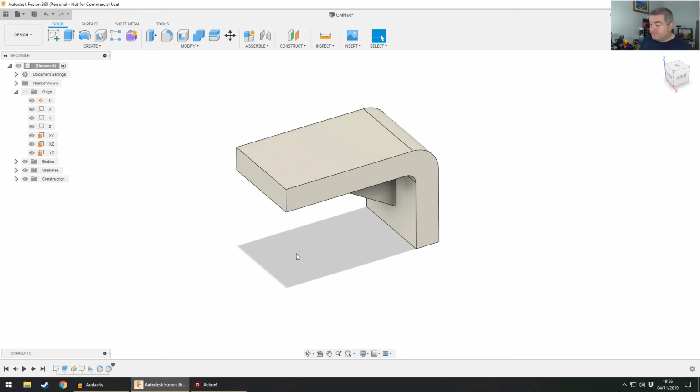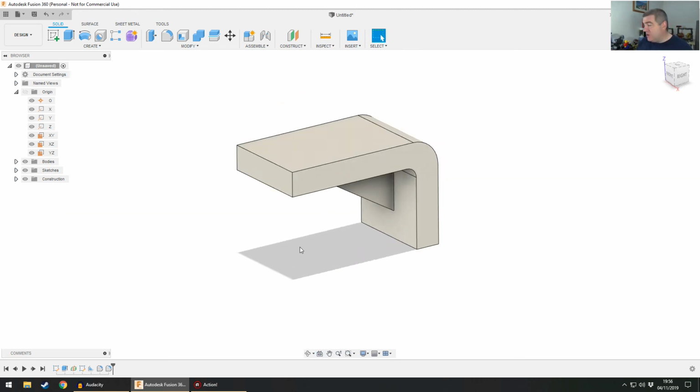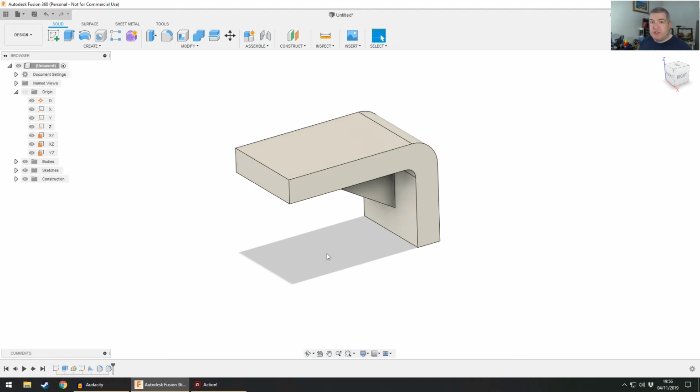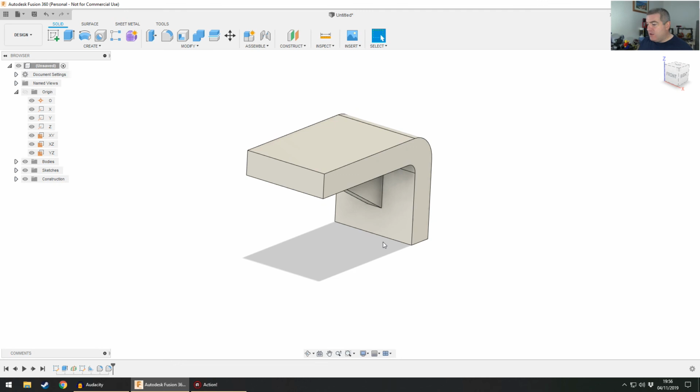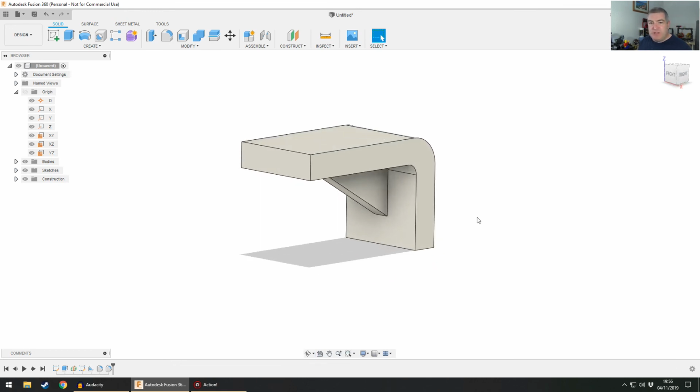That's crazy. But yes, that is a little more information on design intent and an introduction to the 80-20 rule. If you want to model something and you think, oh, it's absolutely crazy, what a weird shape, just break it down into big lumps. Create those big lumps first, and then use more features to refine them. Okay? So, I don't want this to be a long video because it's not really that interesting, but it's something you need to be aware of as you move forwards into solid modeling.